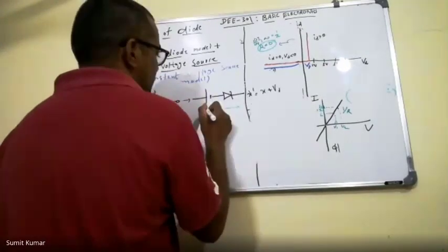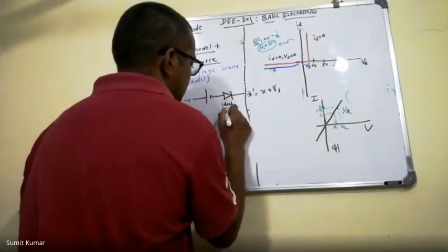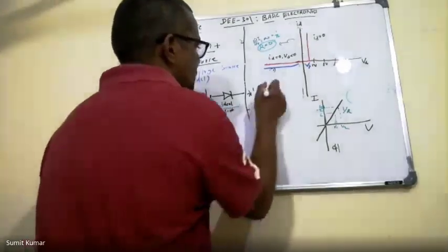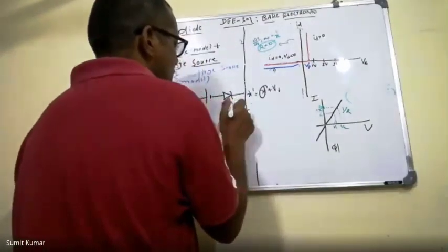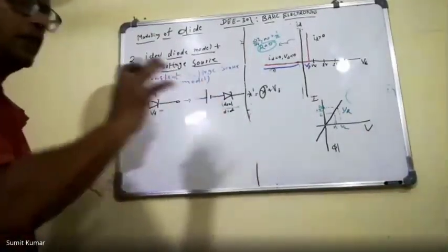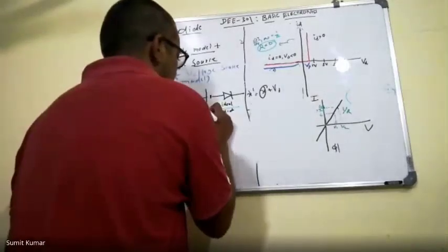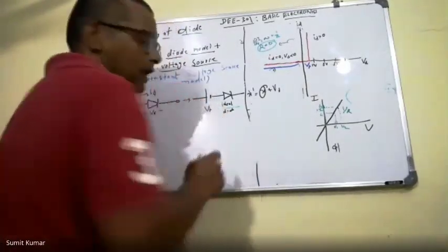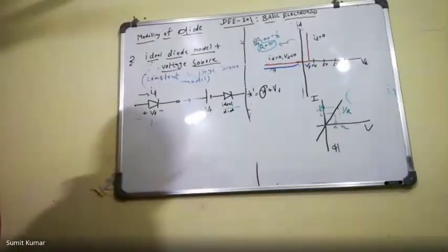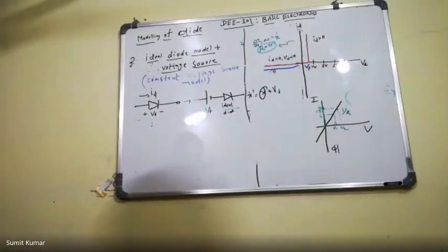Okay, so plus an ideal diode, because you can see this is the modeling for the ideal diode. And if I keep the ideal diode modeling the same, which we have learned in the previous topic, and I just add this value of voltage VF, then I can definitely do the modeling. So you need to understand this is the ideal diode plus constant voltage source modeling.